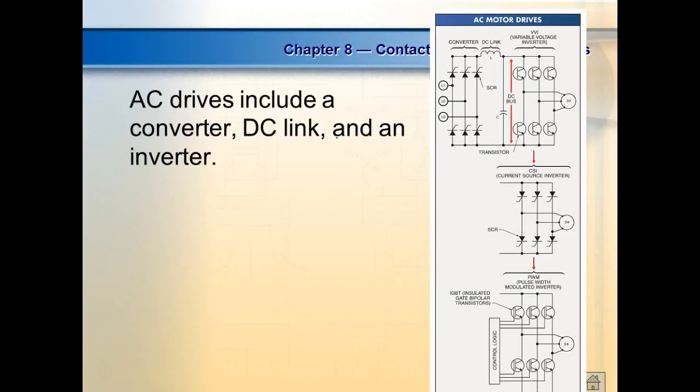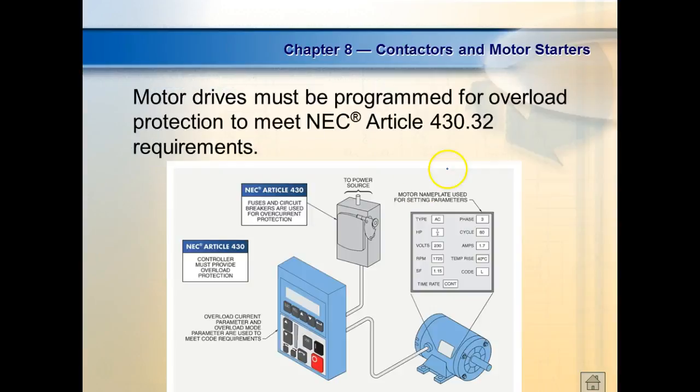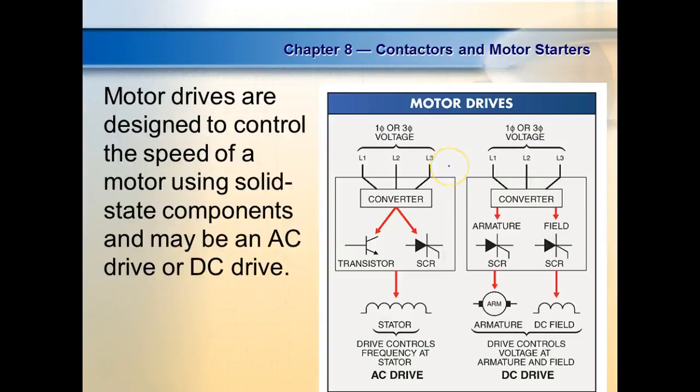Losing means we lose current flow through the field. So this is why on shunt motors and stuff like that, we very seldom fool with the field, because if it's a shunt motor and you lose the power going through the field, well, if you lower the voltage on the field, the motor speeds up.